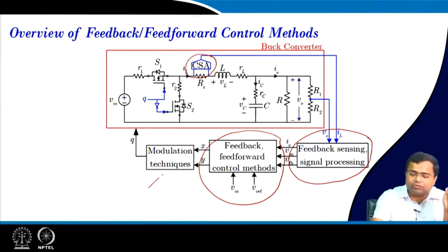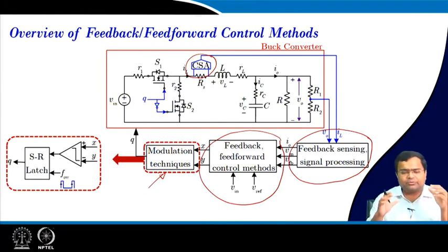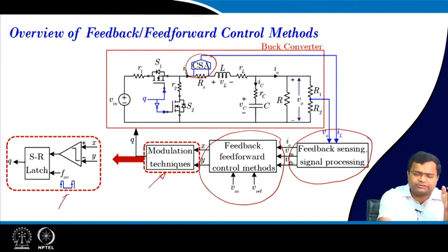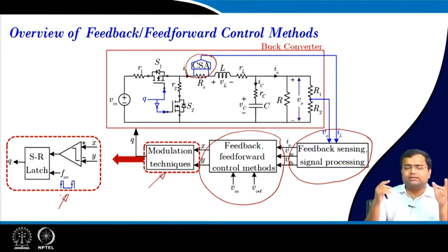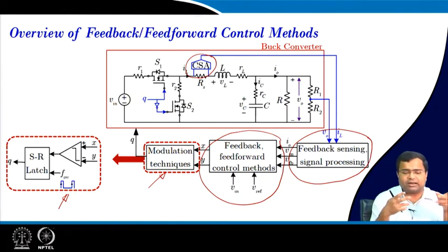So, you need a modulation technique. Here I am showing a simple pulse width modulation by using a latch and a comparator. You can synchronize with a fixed frequency clock, that is why it is pulse width modulation, and by means of a comparator and a latch circuit you can generate the duty ratio of this converter.